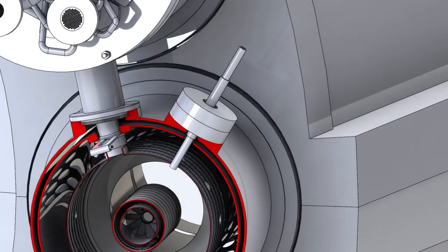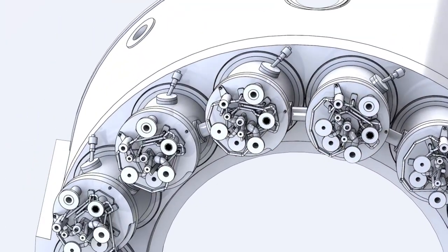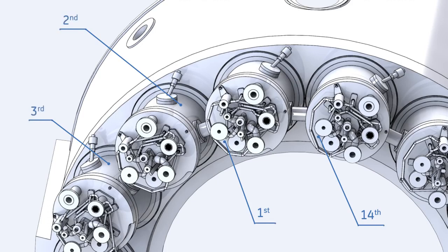On a DLN1 combustion system, spark plugs remain inside the liner throughout all the operation for startup and primary zone reignition functions. Once the flame is started on these chambers, it propagates to the other chambers through the crossfire tubes. Flame is detected on combustion chambers by means of ultraviolet flame detectors mounted on 4 chambers, the 14th, the 1st, the 2nd, and the 3rd combustion chambers.